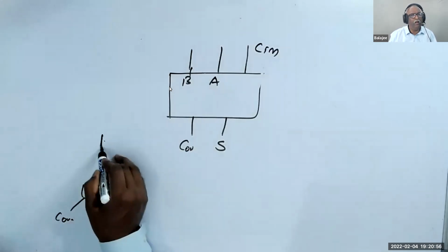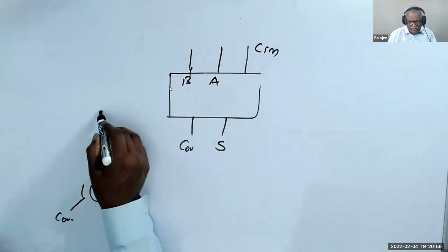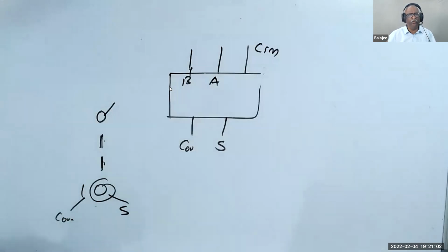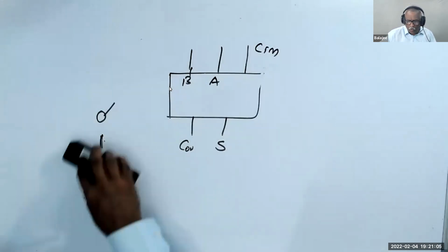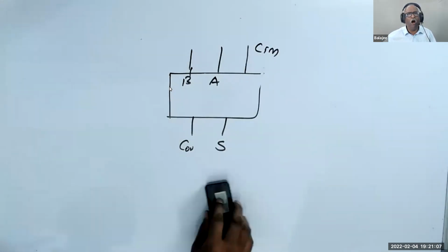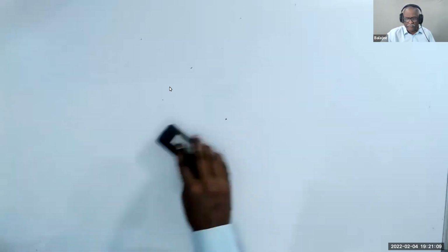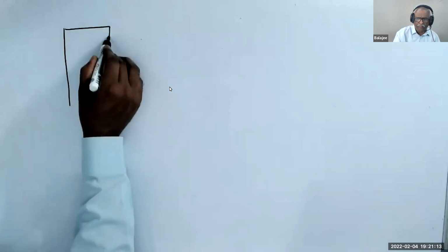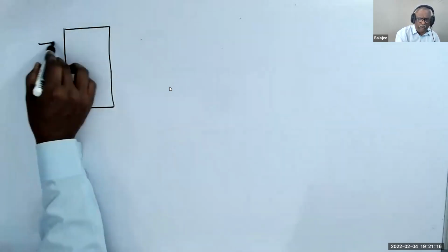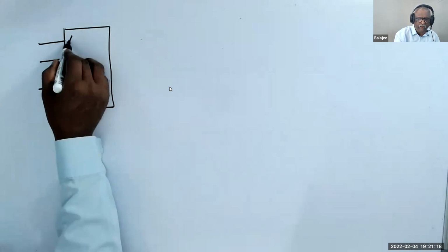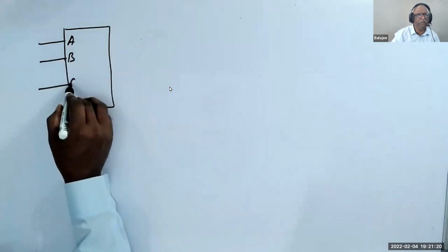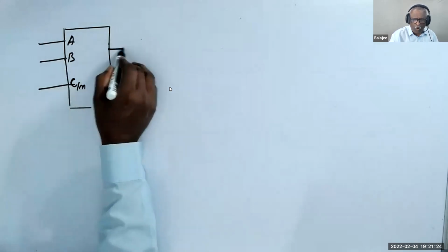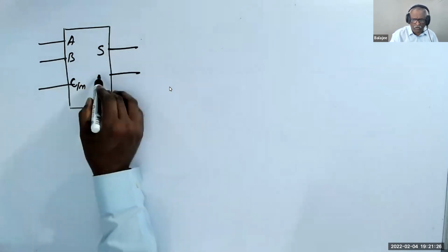And here there are two numbers, but for the first digit alone we assume 0 is the carry in. So we take this as common. Now the trick here is, now I understood, this is what I have to design. I have to design a block of 3 inputs, A, B, C in, and two outputs called sum and C out.